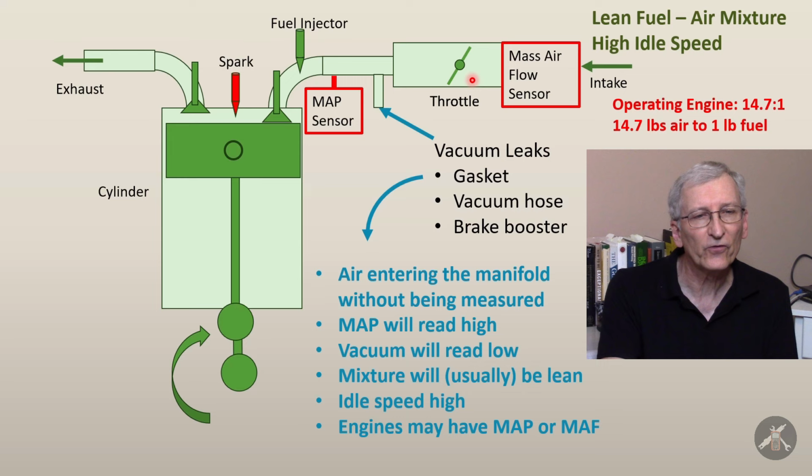Even though the throttle was closed and the airflow was low, this broken MAP sensor, somewhere in the logic, was going, hey, pour in gas, which it was doing. And when we unplugged it, the computer said it's a failed sensor and put in a default backup value, probably based on the throttle position, the engine speed, and MAF. Then the engine was capable of running again until we put a new sensor in it.